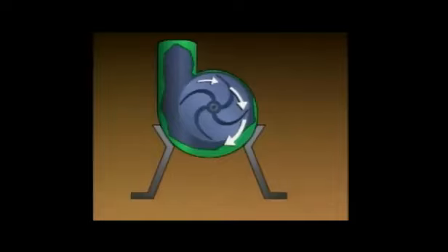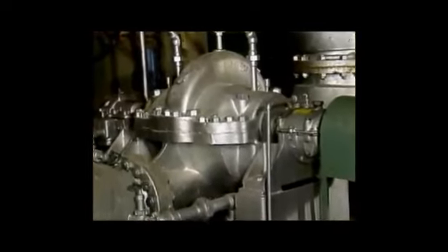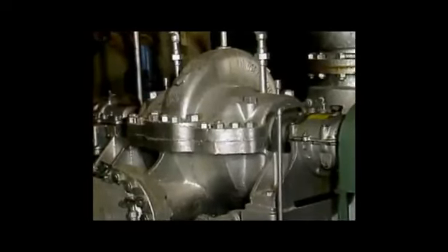As the liquid flows through the volute, it spreads out to fill the increasing area of the volute. This expansion causes the liquid to slow down and its pressure to increase. The increased pressure moves the liquid through the discharge of the pump and then on through the piping systems of the process. All centrifugal pumps work by creating a centrifugal force. This force increases the liquid's speed, and the speed is converted into pressure.